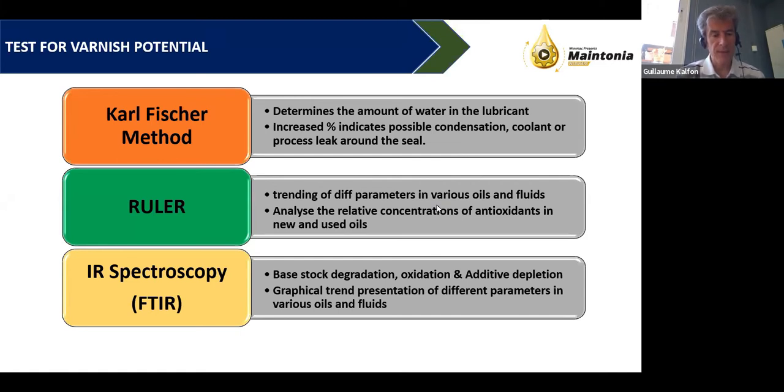It's the ASTM standard D6971. It tells you how old or young the oil is based on the strength of the remaining antioxidants. And the antioxidants are protecting all the other components of the oil. So if they are still strong and still near 100%, then you have long oil life. If they are near 25%, then you have short oil life. Your decisions will be very different in both cases. So this is another test that you need.